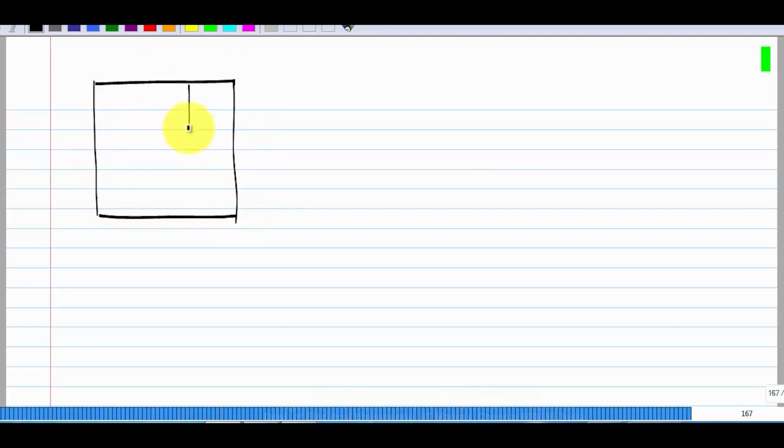For instance, let's say I have a circuit whose graph looks like this. These are all nodes, but of course here I am concerned with currents. Let's say you take the current in the innermost mesh, and if you look at these four branches which enclose the mesh, their currents will not be equal to this mesh current.